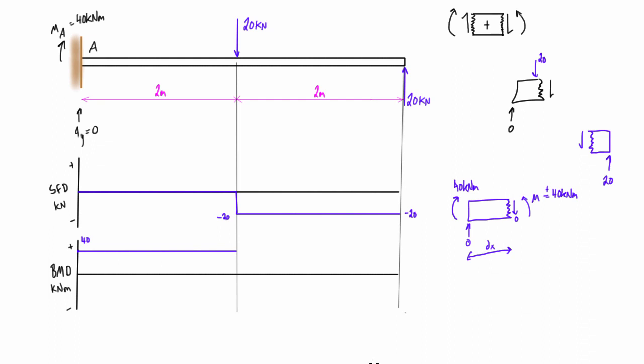We can add on the shear force here of 20, and then as we increase this distance past, basically from just to the right of this over, we're going to be getting this force couple here with an increasing distance between them. Or the faster way to do it, instead of doing this all in terms of x, is just to recognize that this shear force diagram has some area here, like we've been doing in previous videos, and the area here is just equal to the change in magnitude on the bending moment diagram, and this area is on the negative side of the axis, so that is going to push our change in magnitude on the bending moment diagram towards the negative side.